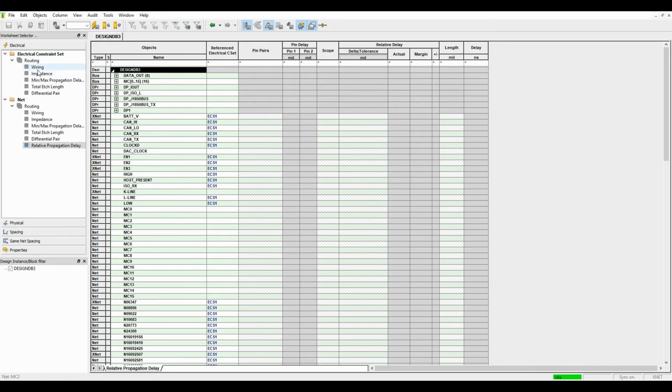So this is really, really key. It's an important step that you have to make sure of. So obviously make sure you send the netlist to the board, and then bring the board information back. So you back annotate that information back to the schematic, and then you can get the two into sync. And this is kind of a continual flow. So from now on, if we need to make changes, make changes in the schematic and Constraint Manager at the front end. We then create the netlist and send that information back to the PCB editor.